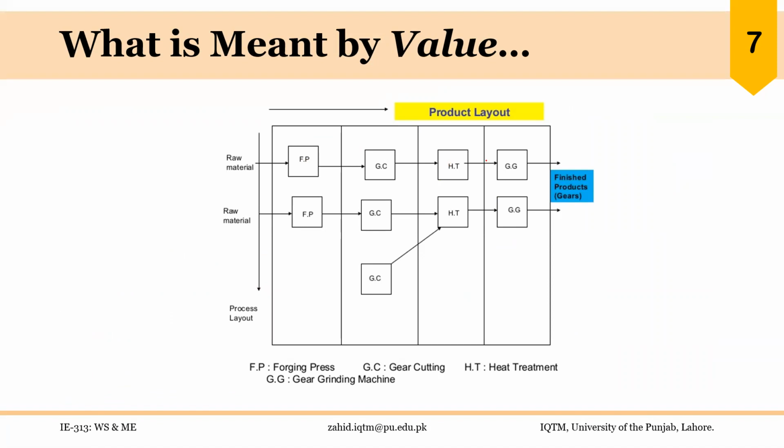As we discussed with the help of this figure in the beginning of our course, the steps or processes where the shape of the product is being changed, the geometry or characteristics are being changed, that is the value adding step or process where the form is being changed or form value is being increased. Whatever is happening in between the processes, whether in terms of queue or wait or delay or transportation, or even unnecessary motions being performed at these workstations, they are all examples of muda or waste, and we have to reduce or eliminate them. And we will see that that is a huge proportion of time spent in the manufacturing life of a product, the time spent between processes or unnecessary motions at a workstation or at a process.